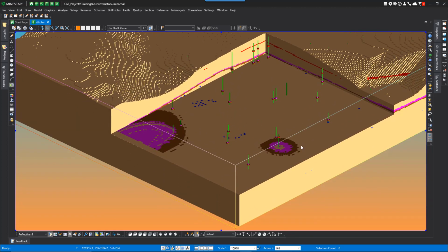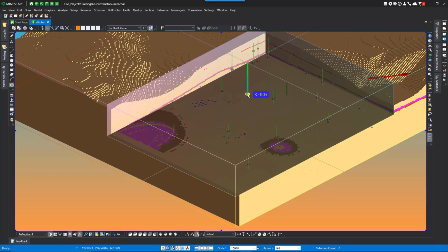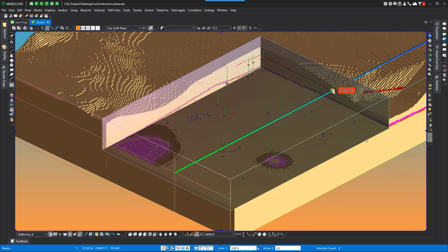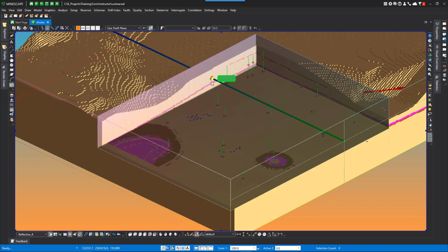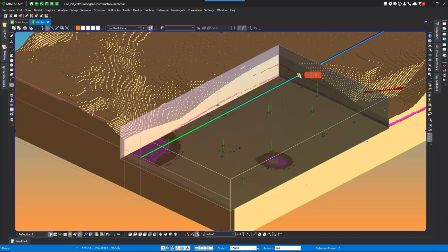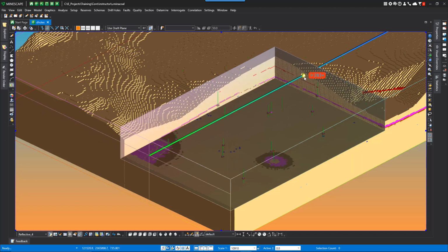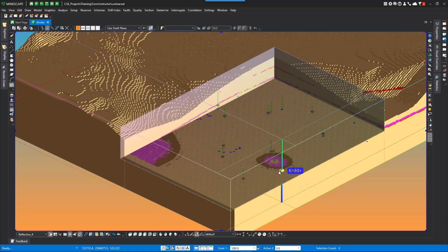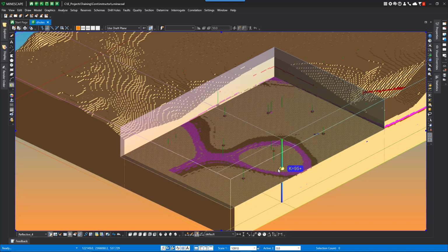We have also included an icon to start the slicing tools and including functionality that can be accessed by the right mouse button. So there's a button down here to start the block model slicing, or you can go to right mouse, start the model section. And if you notice here, we get the axis. So if I just want to take this and slice it, move the mouse, and then let's say we want to go from the I direction, and maybe we'll want to bring it up in the Z direction or the K.